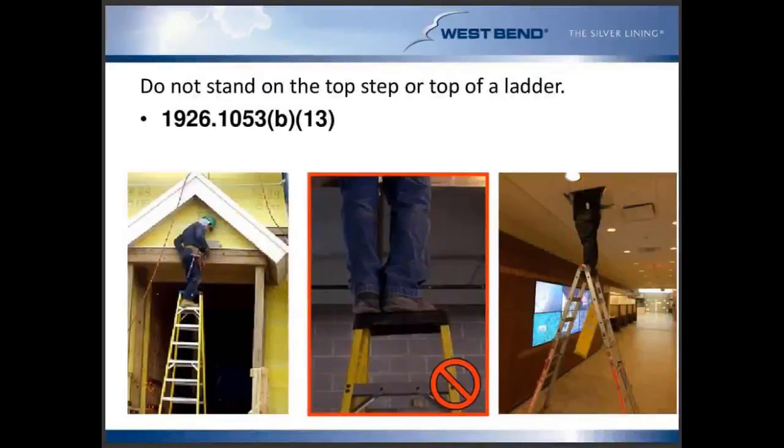Now, as I mentioned before, the ladder labels, especially for step ladders, will state that you cannot step on the top or top step of that step ladder. This is also an OSHA requirement, and I've included the regulation number there for your reference. Obviously, all these pictures you see at the bottom are violations of this requirement, which can be found in the OSHA standard, but also on the ladder labels as well.